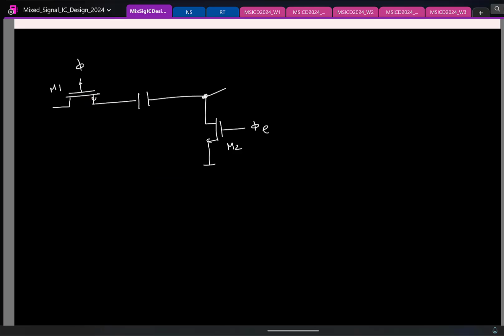So I decide to look at the total charge at this node, and to measure the voltage, I go and ground it and find the voltage, right? But addition of ground won't lead to the discharge. Yeah, I cannot always connect it to ground, right? I'll have to put a switch here. It is connected to ground. What kind of switch will I use? Okay. So now that begs a question. What should be the clock phase for this guy? Phi x.